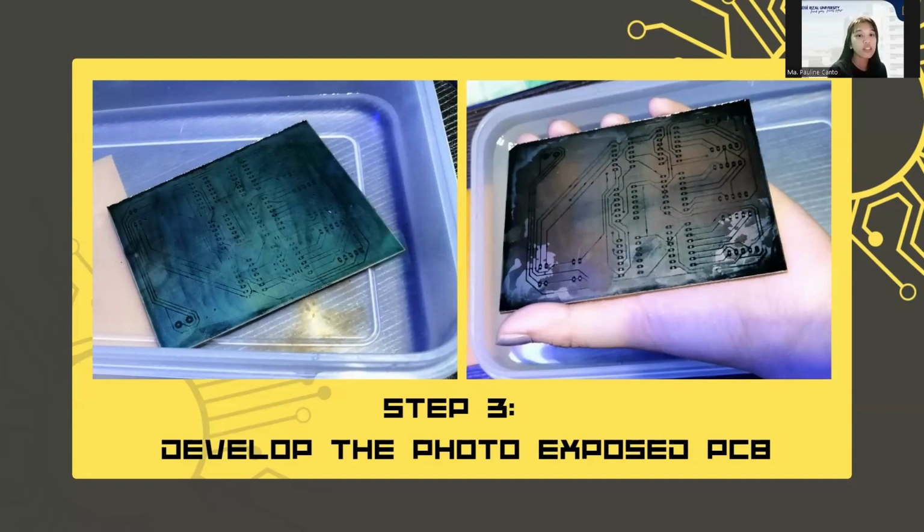Most often, you mix the granules with 500 ml or 1 liter of water. In our case, we used 1 liter of water. We put the PCB in a container with the mixture and waited 5 to 10 minutes until the paint from the unmasked areas dissolved, and then we washed the PCB in running water.